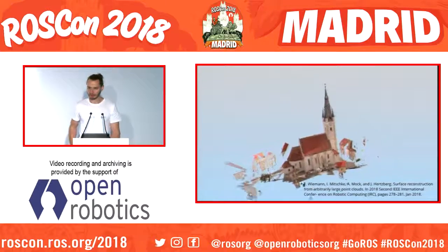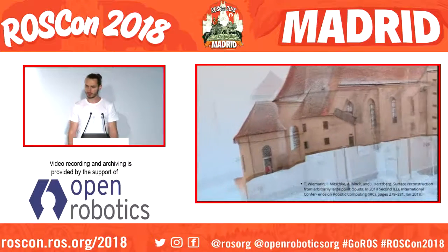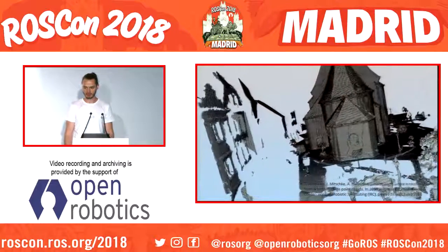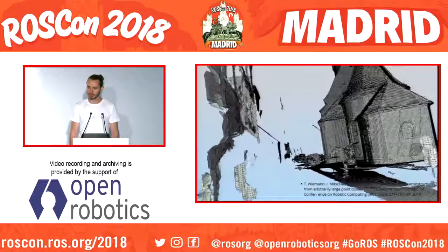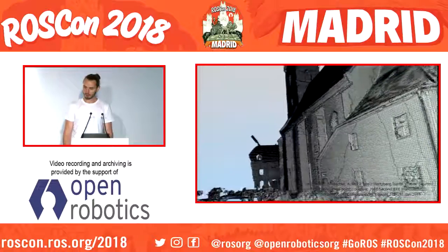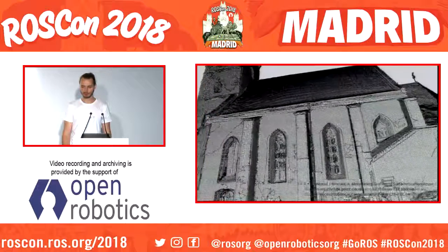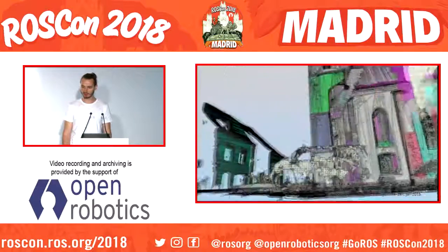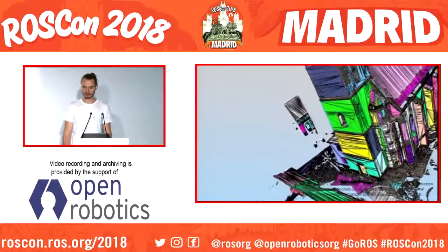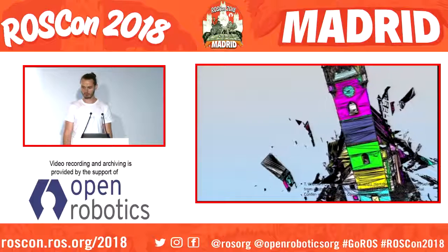So coming from a high resolution point cloud, or many point clouds registered to each other, we can reconstruct these using, for example, the Las Vegas Reconstruction Toolkit, namely LVR, and the marching cubes approach, and then reconstruct it to a mesh, as we see in the video, and then also retessellate the triangles to reduce the data, and later also apply some textures to keep the color information, as we will see now.